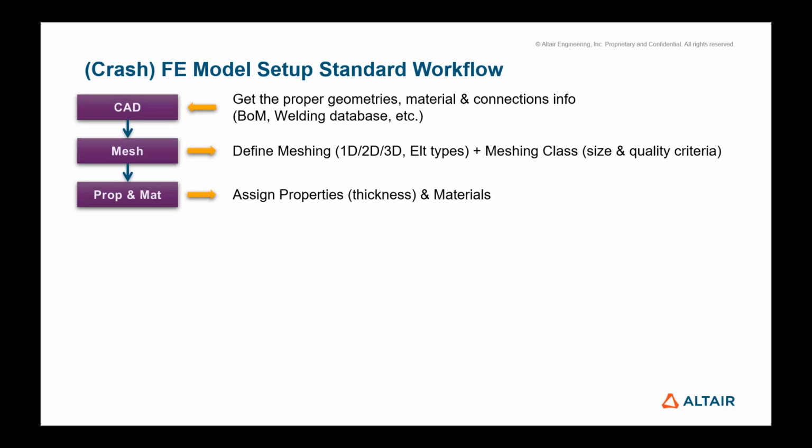First, selecting the appropriate type of material law according to the type of behavior it is and to the data we have. And then, determining the corresponding parameters to fit the data. The data may come from test results or be found in literature, but keep in mind that for crash analysis, one cannot be satisfied with the elastic characteristic of a material, and its post-yield behavior must be characterized or estimated. That is to say, one needs to look for plasticity and even strain rate dependency and rupture.